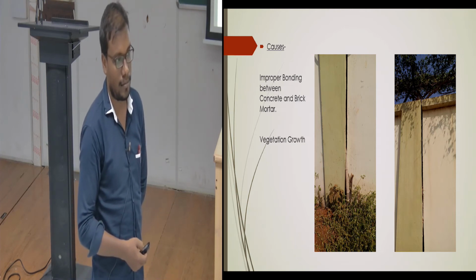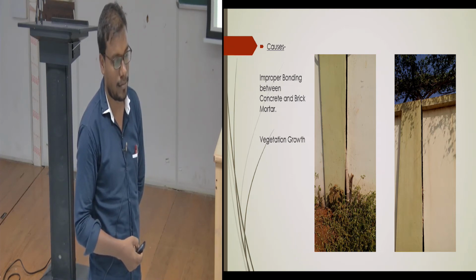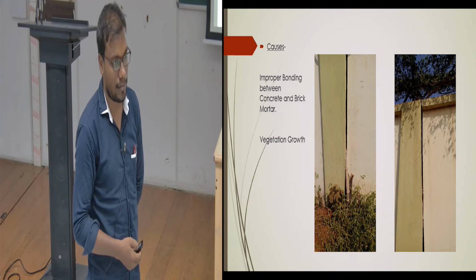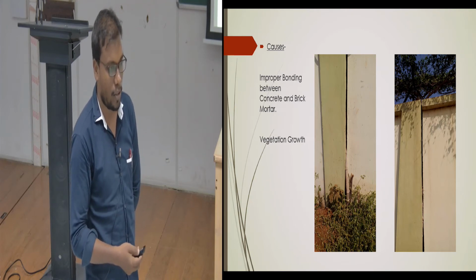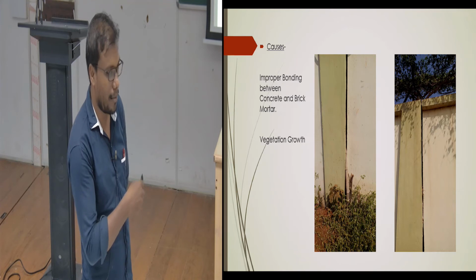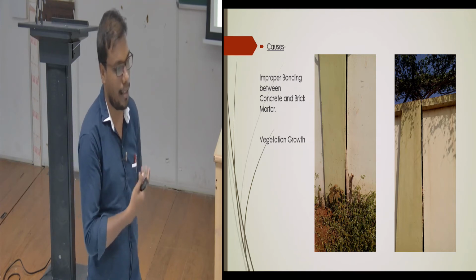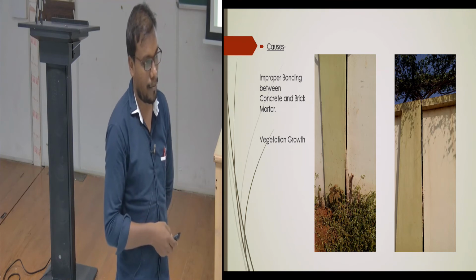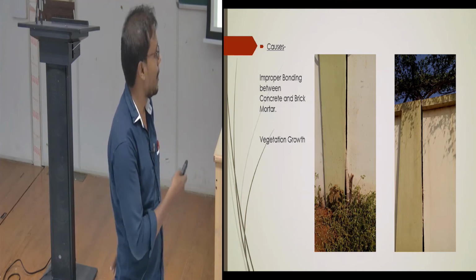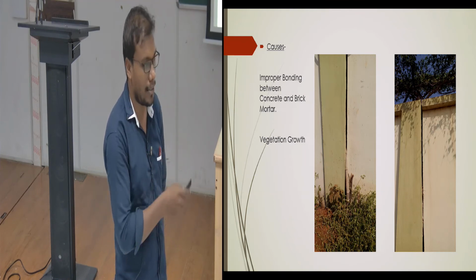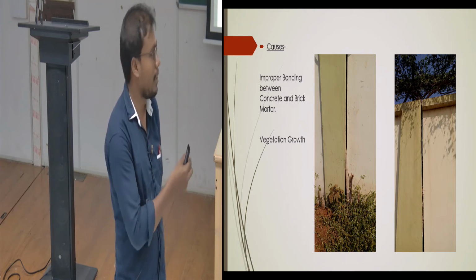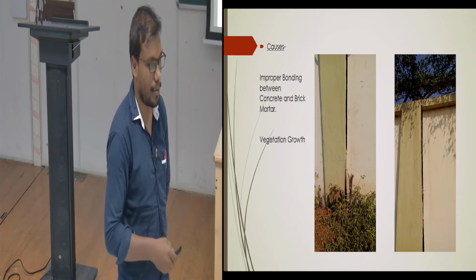We can see that by identifying similar panels. Yeah, so many panels are there. Even maximum panels have cracks. So we can say the main reason was the severity. Yeah, it was severe as well as having vegetation. That's why I took that picture. And the crack width was more. That's why I took this.